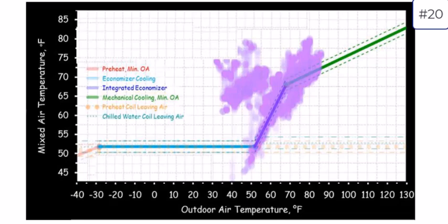that can still operate its dampers and mechanically cool at the same time. And with this specific ratio of minimum outside air required, we would expect the dots on this chart, representing individual instances of it's this temperature outside, and at that moment it was this other temperature for mixed air, to follow the plot. Why aren't we, and what does it mean? How do we interpret it?